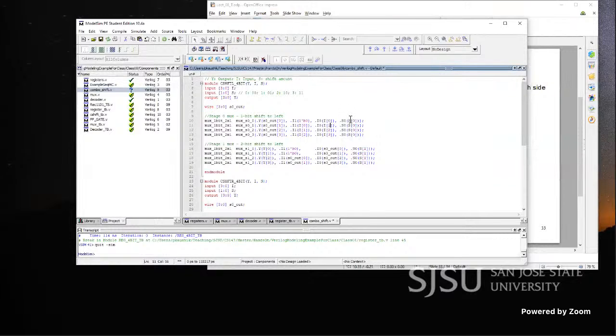Now, if it is a shift, let's say a 1-bit shift or 3-bit shift, at this point my S0 is 1. So I need to do a 1-bit left shift, and we assume that from the LSB side a 0 will be inserted into the shift position.